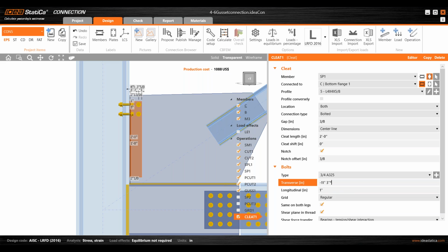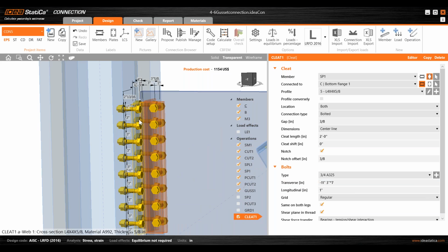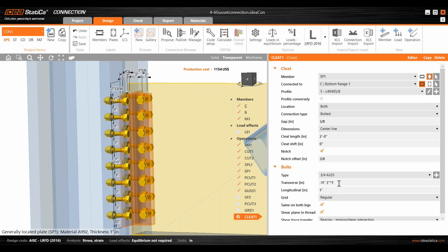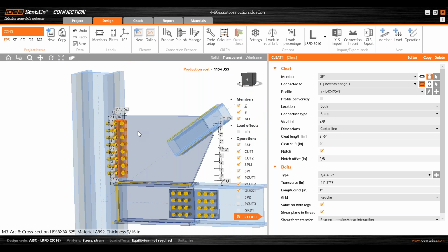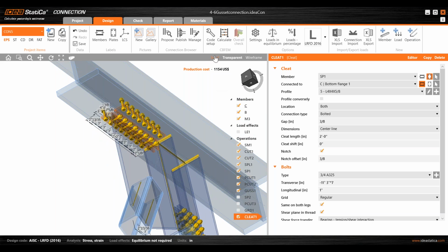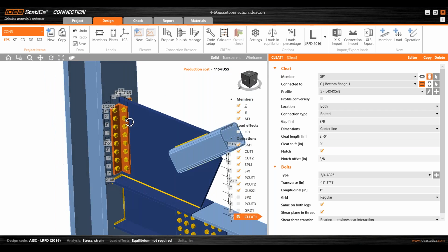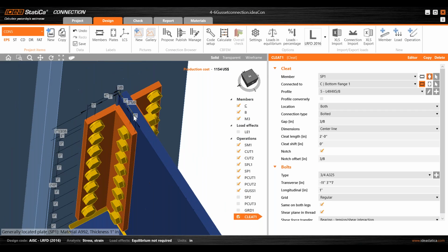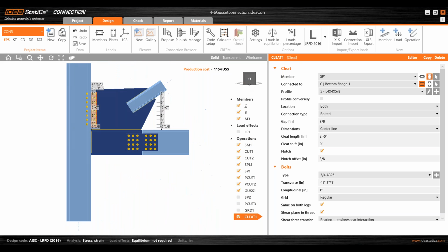And then the asterisk and adding 7 bolts over there, right? I always recommend to delete these coordinates and start typing the coordinates just so you learn how to add those bolts in every operation. So now if you rotate, you can see that with that operation we are connecting both angles to that gusset plate. Okay, so it is very useful.